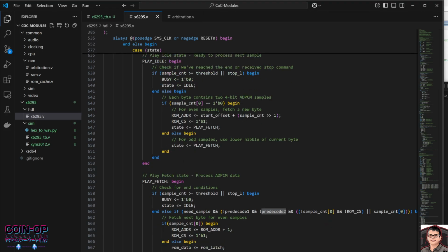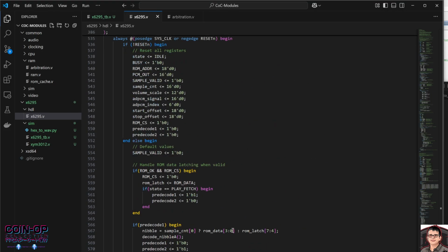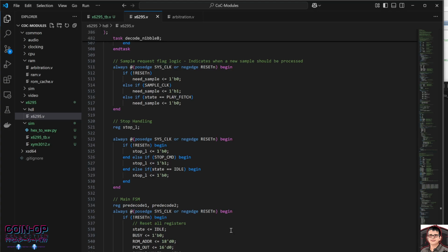And then after that, I convert the ADPCM data to the integer form, right? From this fixed floating point format, and then I increment the sample count, and I do it all over again. So this loops until it reaches the sample threshold end, and then it issues a stop, and that's the end of the pipeline.